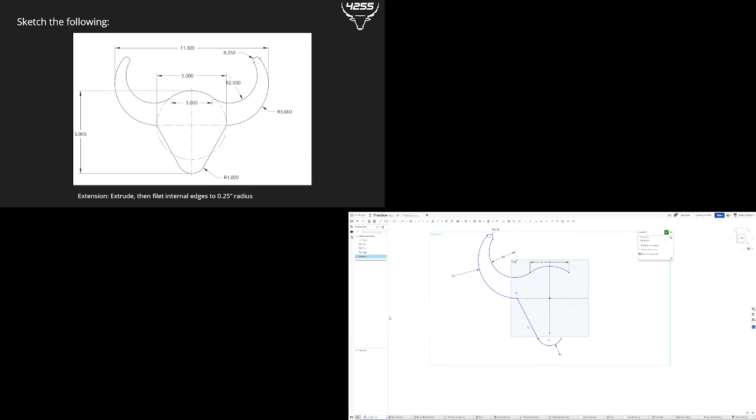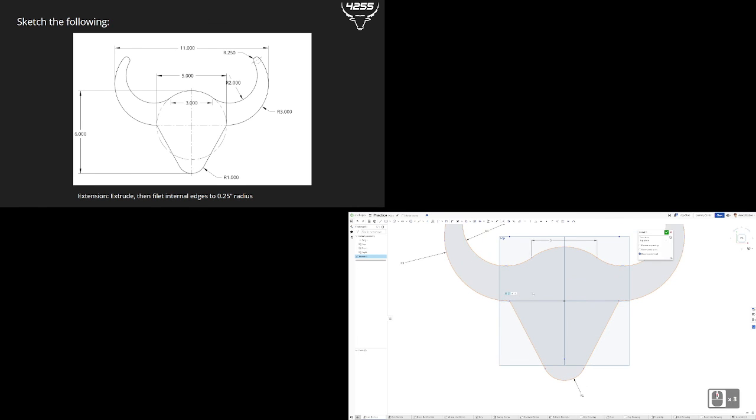I guess what I could do is just mirror everything over and then add the dimension as it's given in the drawing. So I'm going to select all my points, or all my lines here. Or actually, that's bad practice. I'll press the mirror key first. So I'll press the mirror button up here, select my center line, and I'll select this center line of the whole sketch, the vertical plane. And then I will select all the components that I want to mirror over. So this line, this arc, and this arc. And it's starting to look a little bit like what I was going for now.